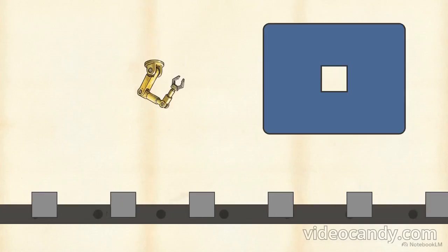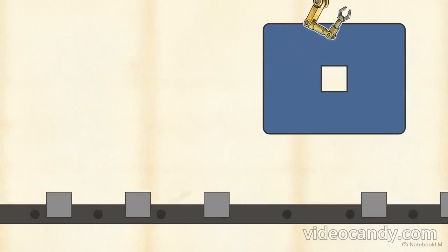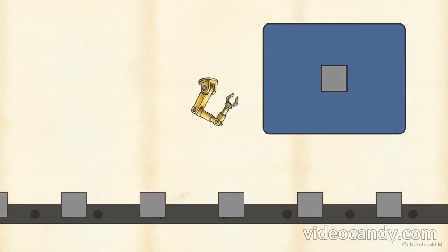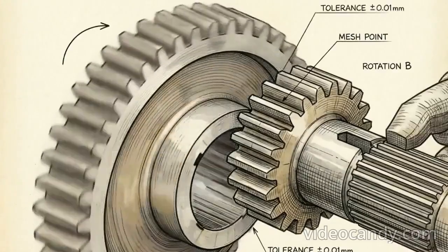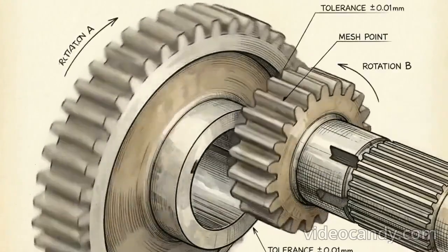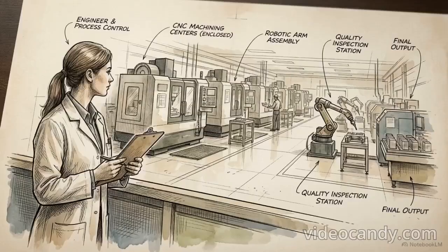In mass production, the components for a single machine are often sourced from dozens of different specialized shops. To manage this, we rely on metrology, the science of measurement. It provides the strict dimensional control required to ensure decentralized parts are accurate. The goal of this system is interchangeability. Any part selected at random must assemble correctly with any other matching component. When these principles are applied correctly, we see disparate components sliding together to form a finalized functional engineering assembly. Manufacturing engineering is the mastery of this entire sequence, from classifying the raw material to verifying the final dimensional assembly.